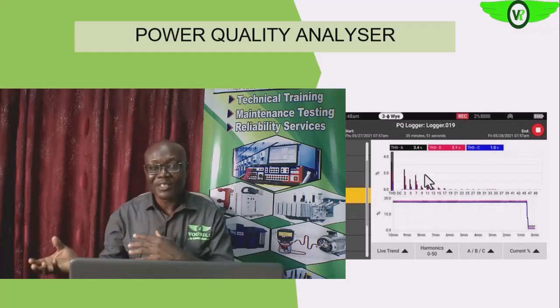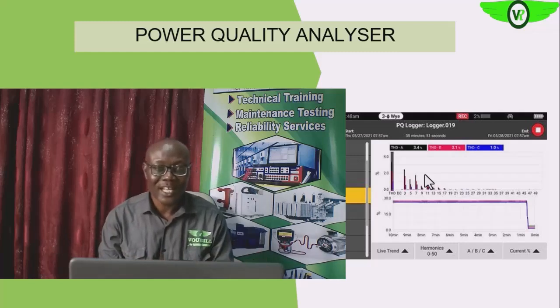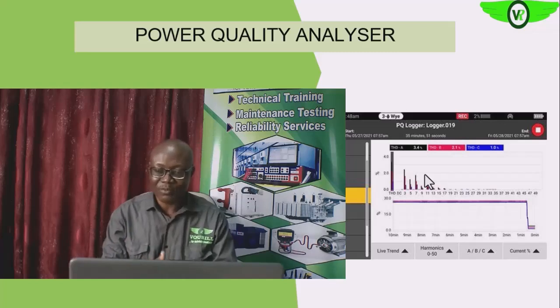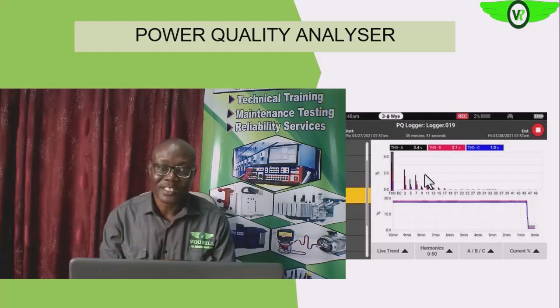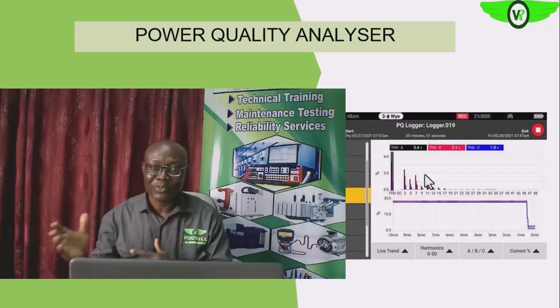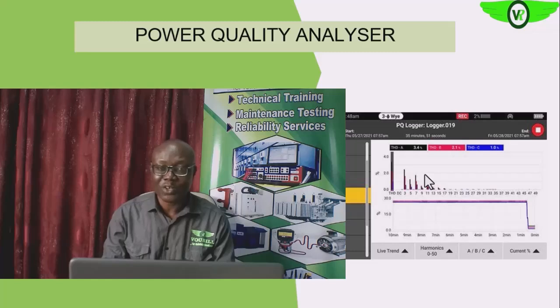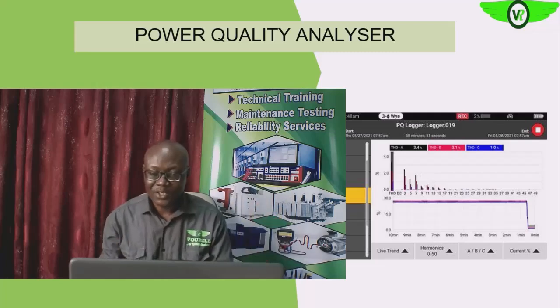They also have the effect of introducing such harmonics that will become problematic if we do not take care of them. When such happens, we also see them in the system as we are monitoring, as we are moving away from the input point, or the point of common coupling between your facility and the utility.